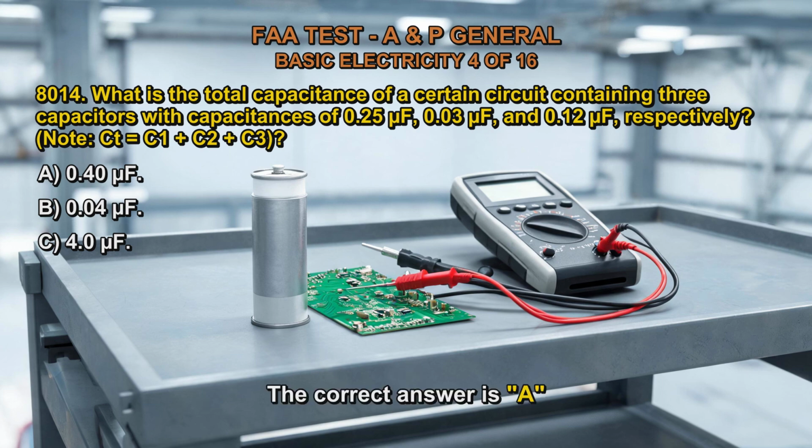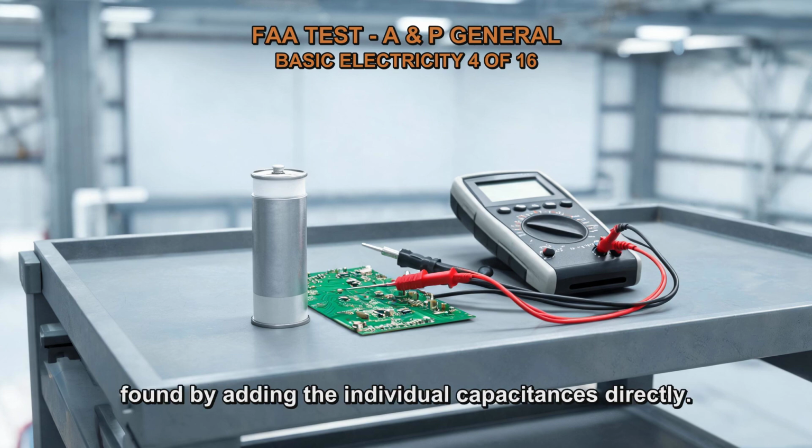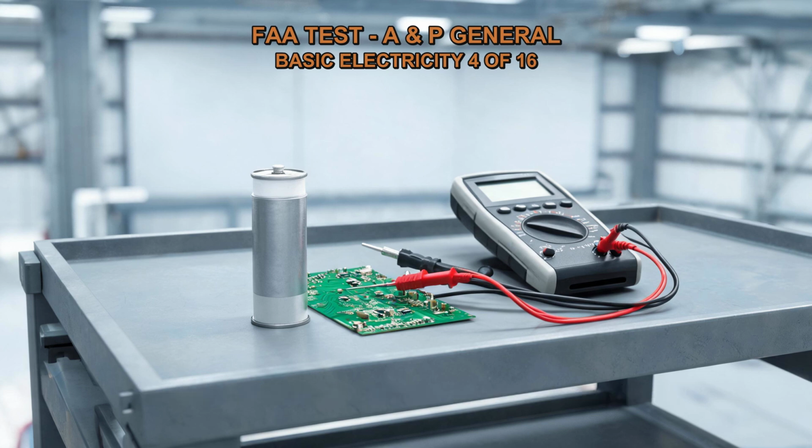The correct answer is A. For capacitors connected in parallel, total capacitance is found by adding the individual capacitances directly. CT equals C1 plus C2 plus C3. CT equals 0.25 plus 0.03 plus 0.12. CT equals 0.40 microfarad. Therefore, the total capacitance is 0.40 microfarad.